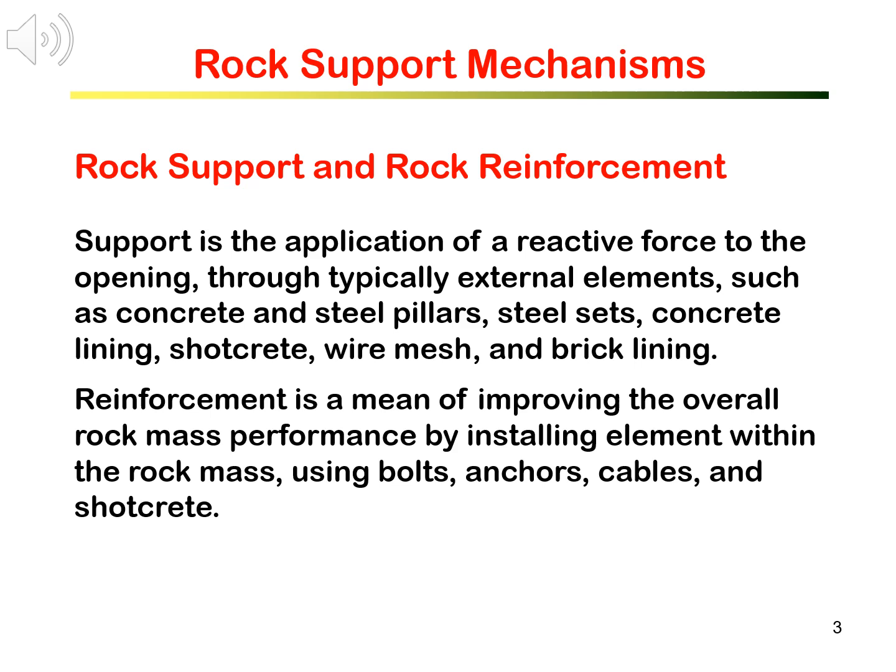Rock support is to apply external elements to deliver reactive pressure to the opening, roof, and wall. The common external elements are pillars of timber and concrete or steel, concrete lining, steel sets, wire mesh, and shotcrete. In old days, tunnels were supported by timbers and bricks.